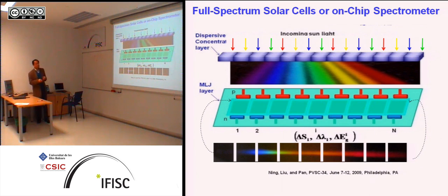That's why people work on multi-junction solar cells, stacking 3-4 junctions. But the problem with stacking multiple junctions is that you have to find 3 right band gaps on a given substrate, which is very difficult.